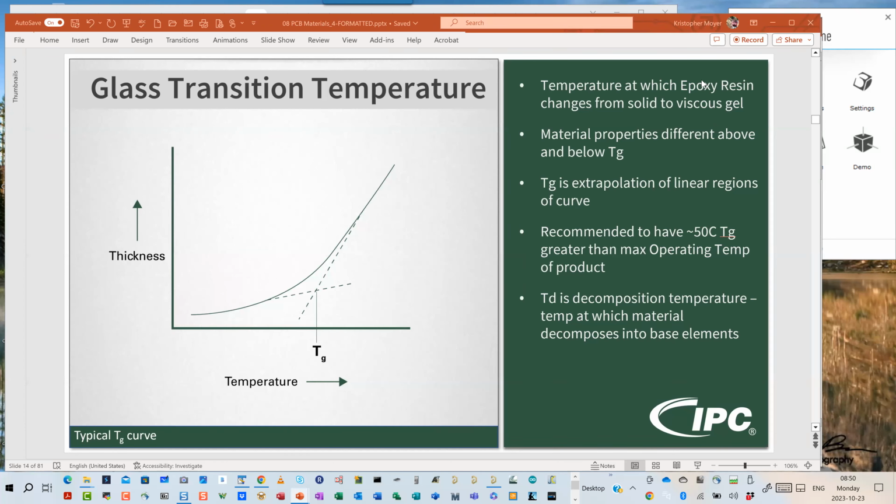Right. So that is actually what I think we're seeing, because I think that at 175 also resistors were not terminating as they were supposed to be terminating anymore. Yeah, okay. You took your poor little 22 or 33 ohm resistor, and now it's like 50 ohms or 60 ohms or whatever it is. It's like, well, it's doubled its resistance, so now I've got all kinds of crazy things happening. Yep. Okay, thanks. Exactly what I would expect to start seeing.